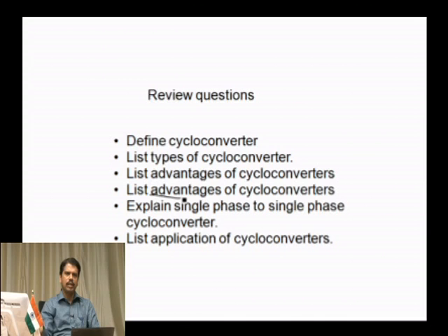We have seen the range of power, in megawatts. The maximum range is up to 150 megawatts. The particular cycloconverter I have shown is 36 megawatts, used for very high torque synchronous and induction motors in rolling mills, in steel industries, even the mining industry.